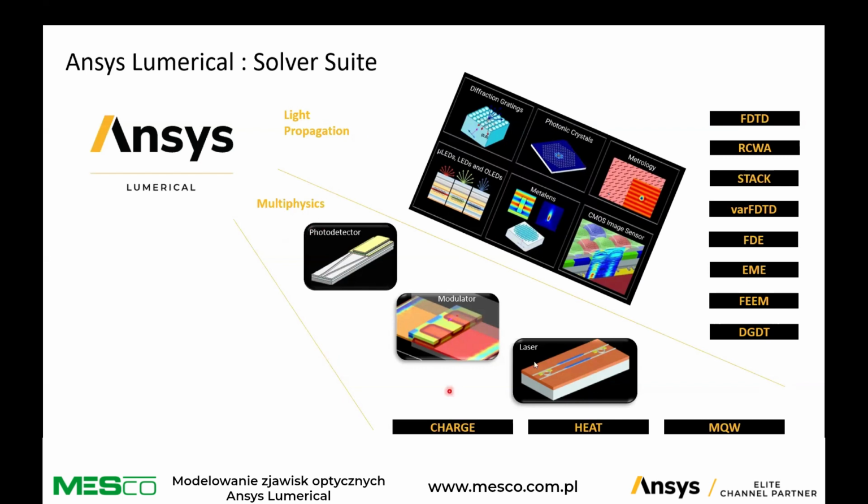And the other one, again, similar to the modulator, or to the photodetector, sorry. If you have light absorption in your device, let's say a plasmonic nano antenna, you can use this absorption as a heat source in the heat transport solver, and then get the temperature elevation that is induced by the absorption.